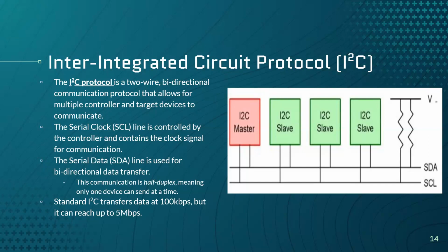So you can think of this device as actually going to take the SDA line and ground it. And that's going to send it to a logic level 0. And that initial change is what signals for the communication to occur. Once that happens, then it can send its commands based on how the I2C protocol works. Does that make sense? No, not at all. Okay. It's grounds that holds it down.